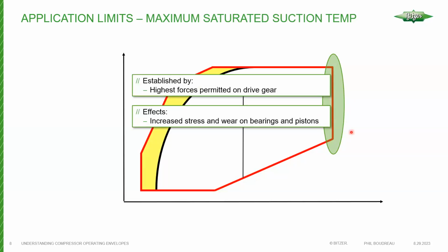This area here, your maximum saturated suction temperature, is established by the highest forces permitted on the drive gear. The effects of this are increased stress and wear on the bearings and the pistons, the wrist pin, for example.